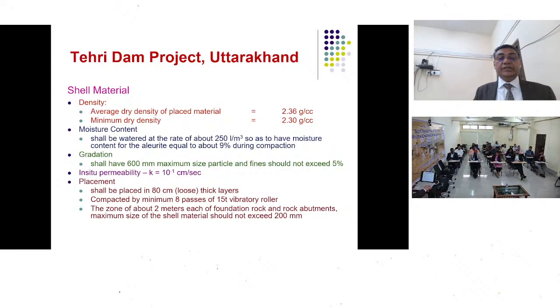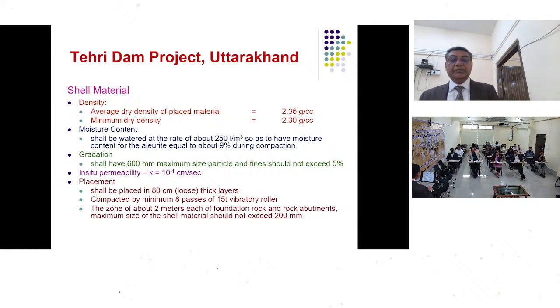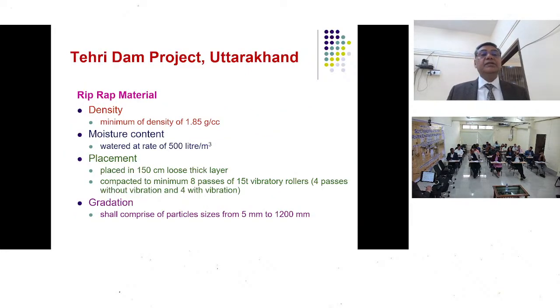Gradation shall have 600 mm maximum particle size, in situ permeability as specified. Zones about 2 meter each of foundation rock and rock abutments. Maximum particle size of the shell material should not exceed 200 millimeters.